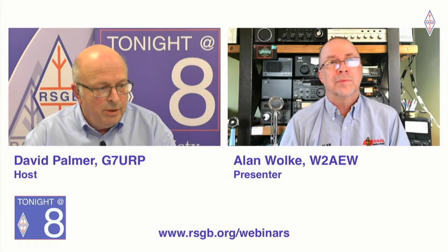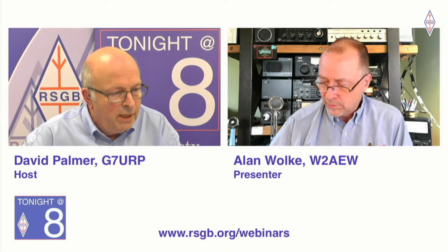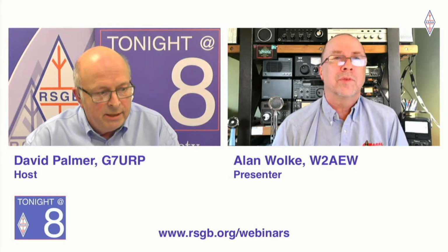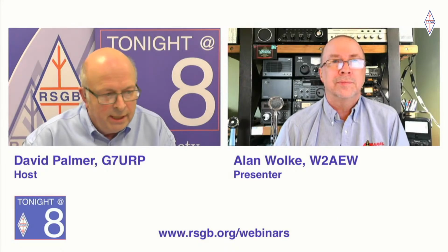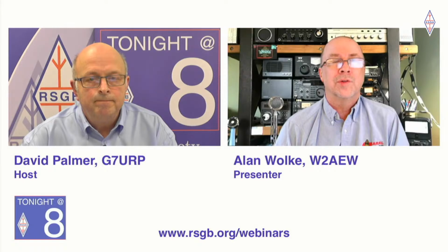Got another question now from James Kelly. Says, can you calibrate across most of the HF band, i.e. run the cal with a sweep from 3 to 30 megs, or is it best to cal on a focused area of interest with a smaller BW, which I guess is bandwidth, i.e. a 4 megahertz sweep centered on 7 megs?